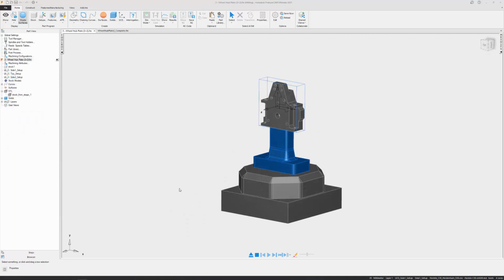We're going to continue the machining of our wheel hub plate. Previously, we did our first operation on just our Haas VF4, simply facing and drilling the holes on what we can now see as the bottom side of our part. And now you can see we have a part here where we have imported some fixture solids to hang on to our part and make sure through simulation that we're not gouging anything. I've selected these as clamps. And you can also see that I've brought in that STL that we saved out to be used as our stock in this case. This will make sure that we don't end up machining anything that we already have.